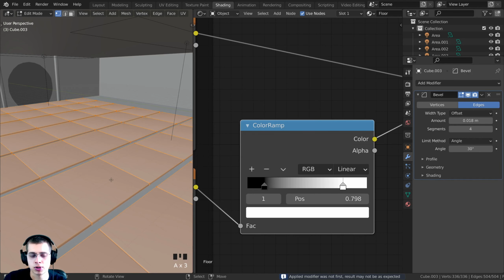So now if we tab into edit mode, you can see they are all geometry. So now in edit mode, I can press U, and I just want to do the Smart UV Project, and then just click on OK. And now if we press Z and move our mouse up to go into rendered view, you can see that looks a lot better. Now again, the texture is a little bit too small, so I'm going to click right over here on the UV Editing tab, and I can just press A to select everything, and then I'll press S to scale, and we are going to scale it up a bit, just like that, so the detail is a little bit better. Let's zoom in here. Yeah, that does look a lot better.